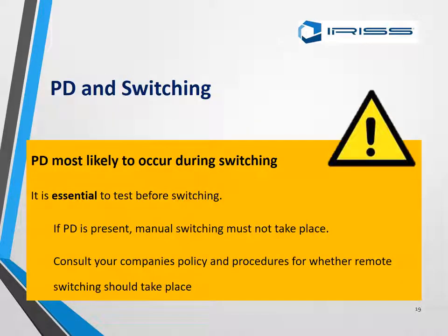Really, it's a rule of thumb that it is essential to test before switching. So if PD is present, manual switching must not take place. What you need to do then is consult with your company policy or procedures to see whether remote switching should take place.